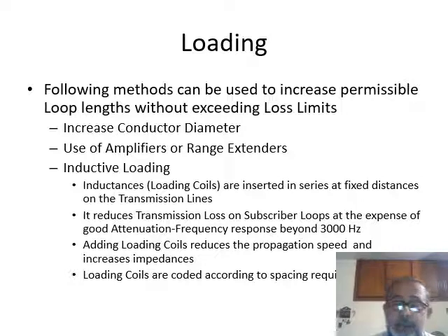That inductor would be of a certain value, a certain number of henries, and it would be placed at certain distances, and it would counter the capacitance that has been incurred due to the parallel conductors going along.